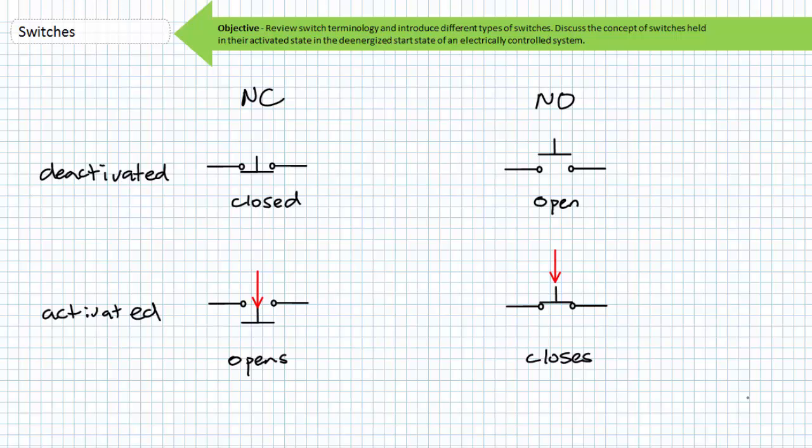The switch, prior to being hit, punched, poked, flicked, twisted, diddled, or dorked with, had a natural deactivated state to begin with. All schematics, all the time, are always drawn in their depowered state, a point I will come back again and again to tediously belabor. We'll soon discuss switches held in their activated state when the system is depowered. However, for now you must simply understand and differentiate between the two mutually exclusive states of deactivated and activated.